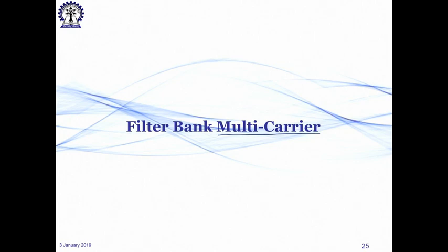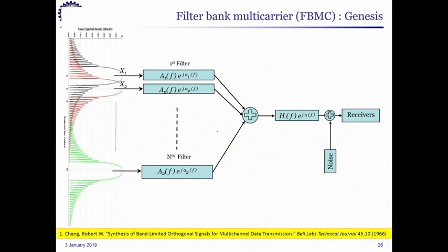We had described earlier how these different schemes do come under an overall group of multicarrier combinations, multicarrier communications, and we are talking about filtering, and there is a bank of filters. So, let us look into the details of it. So, in case of filter bank multicarrier, what we see is that there are different carriers. So, this could be first carrier, this is the second carrier, rather these are subcarriers. If you put the name subcarriers, then it makes more sense, and this is the nth carrier.